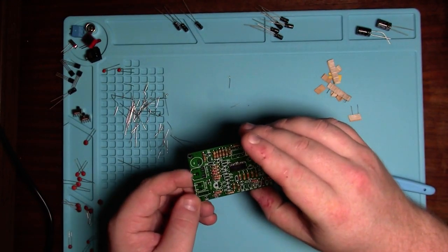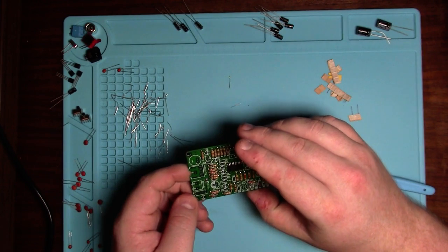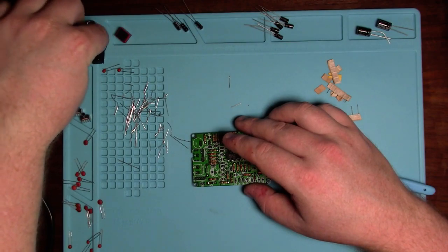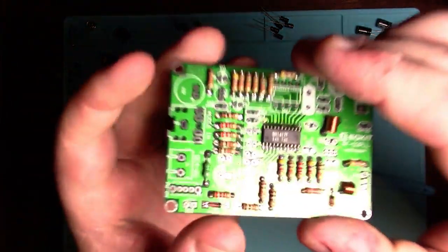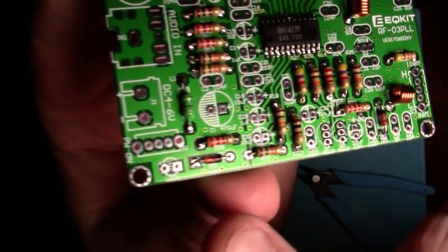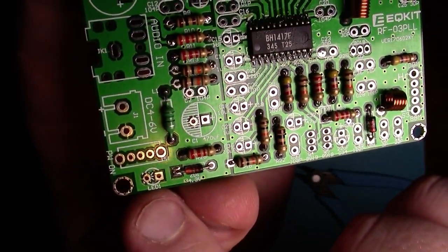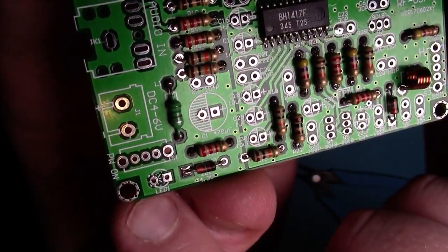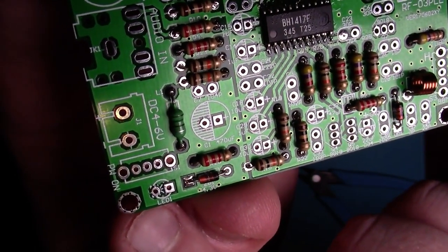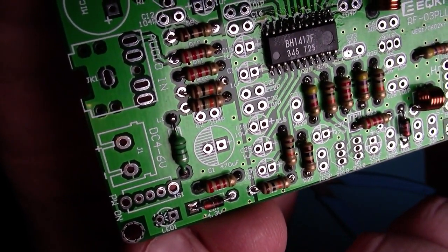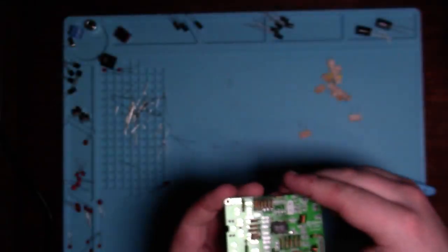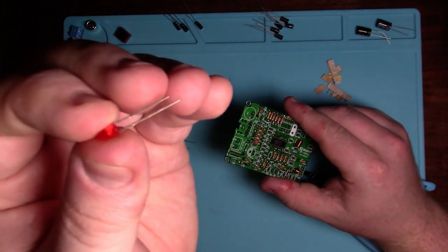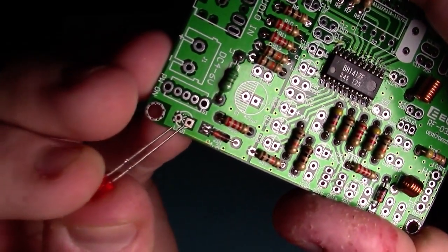And now we have an LED. We can see on here how it's marked. You can see that one section of the board is slightly darkened, and we can see that it's going to the main light green area. So that means this is the negative side of the LED. And indeed, our instruction sheet confirms that. So we want our LED to go in like that.